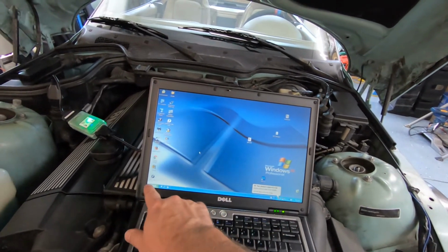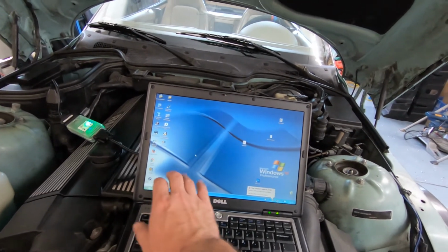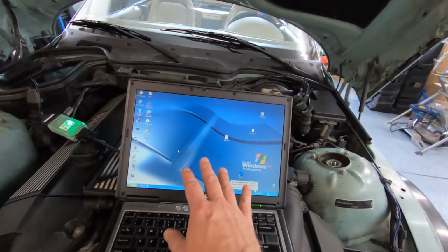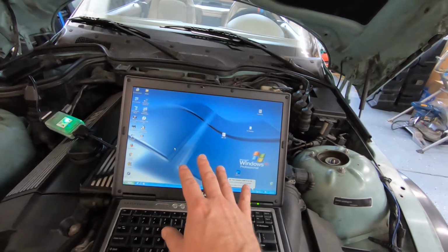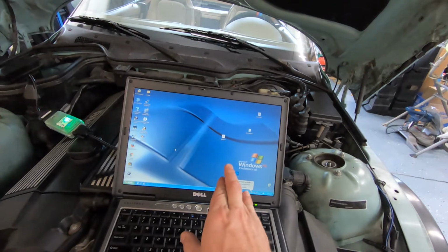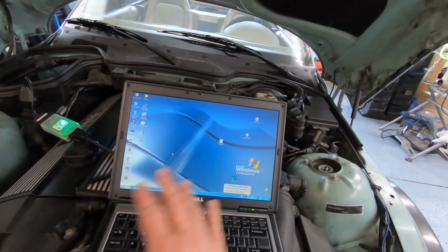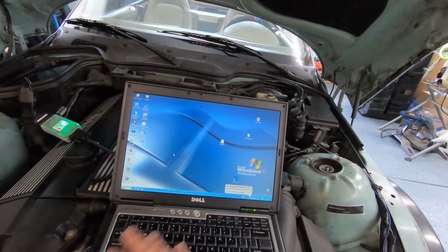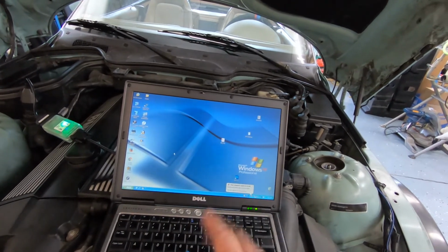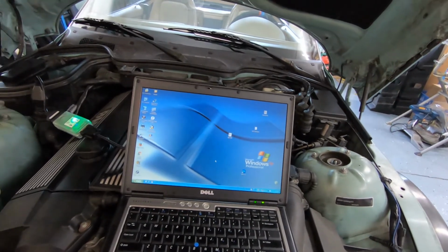Here's what I used. I used INPA. That's basically some diagnostic stuff within a virtual machine, because this is how it was available on the interwebs. I'm running DIS version 44 with GT1, and that is dealer level software that can diagnose, program, and code. It kind of does the whole thing from an electrical aspect of the vehicle. So we'll get into that.